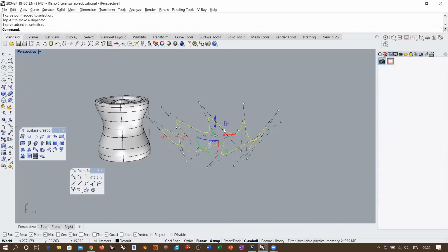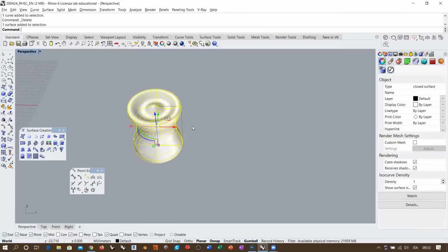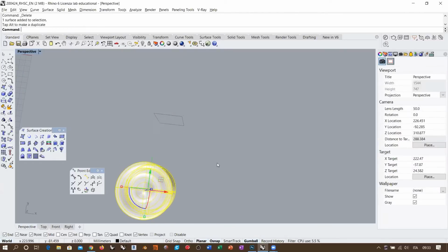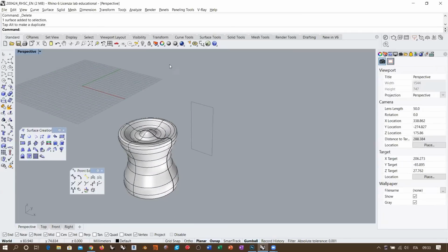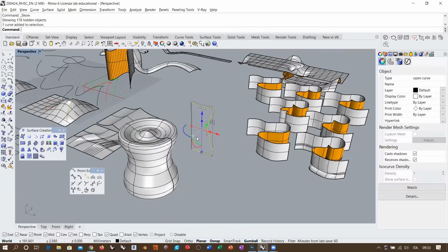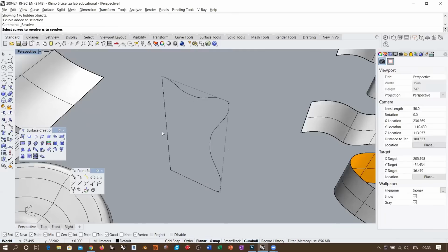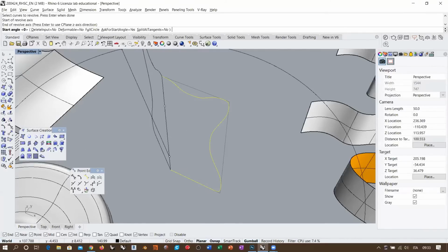Okay. Now, I can also do this with the revolved surfaces, and it's very interesting because if I have this limit of the circle rule in the horizontal direction, what I can do is create a revolve with this profile along this axis, and then I can say I want a deformable revolve surface.